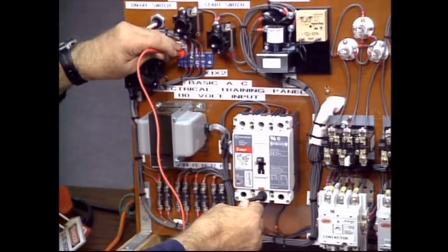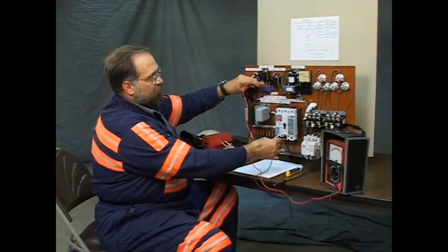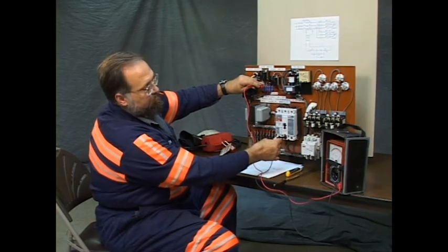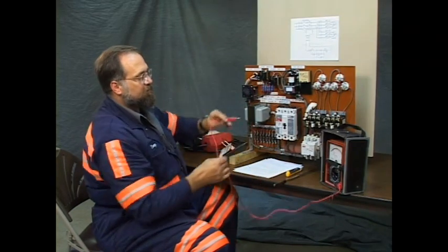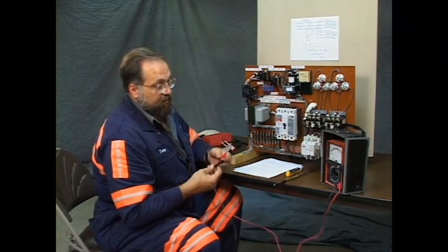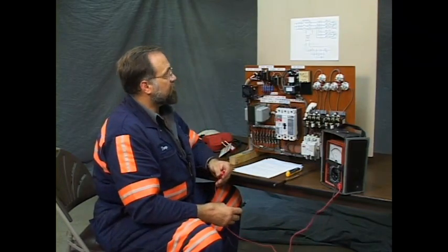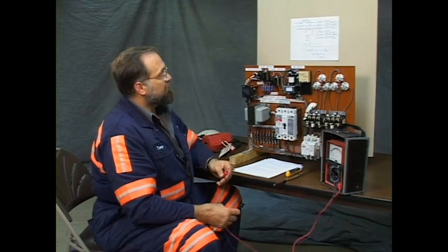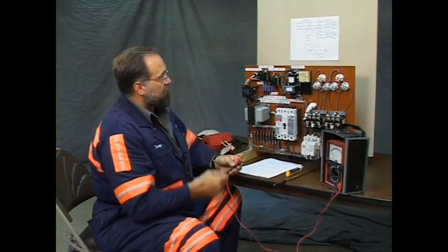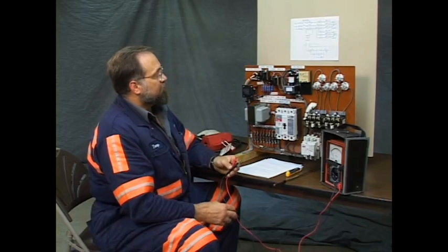It still reads a slight resistance. You know, there are few perfect circuits, and this is reading less than 1 ohm. There's a small resistance there. That could be the contacts of these probes here. I'm not making a good solid contact, but it's a good circuit to the primary of the control transformer.